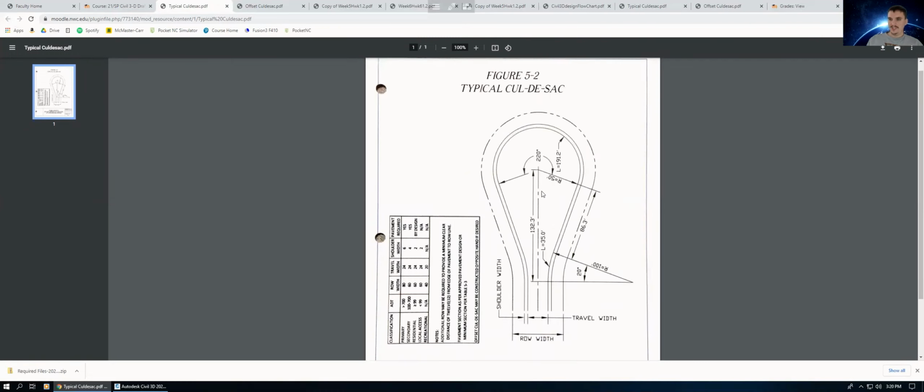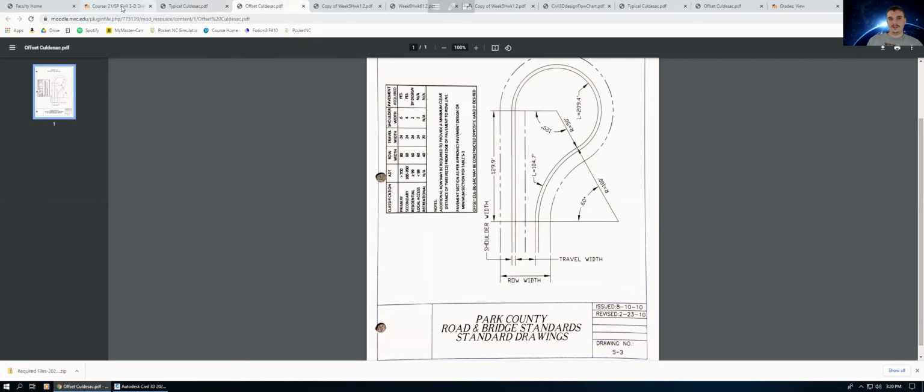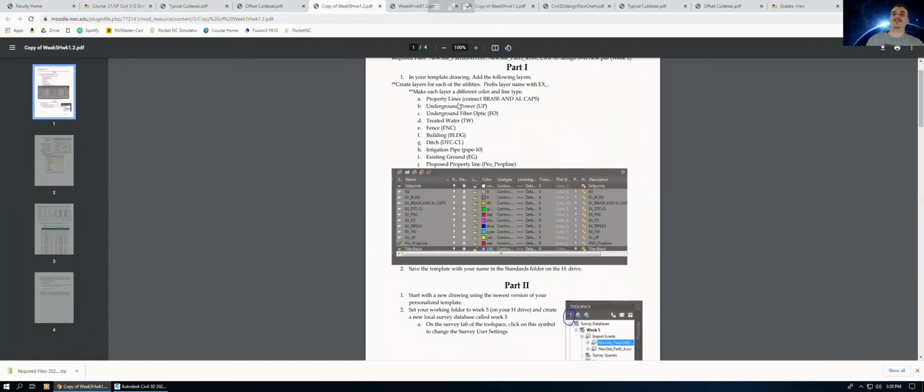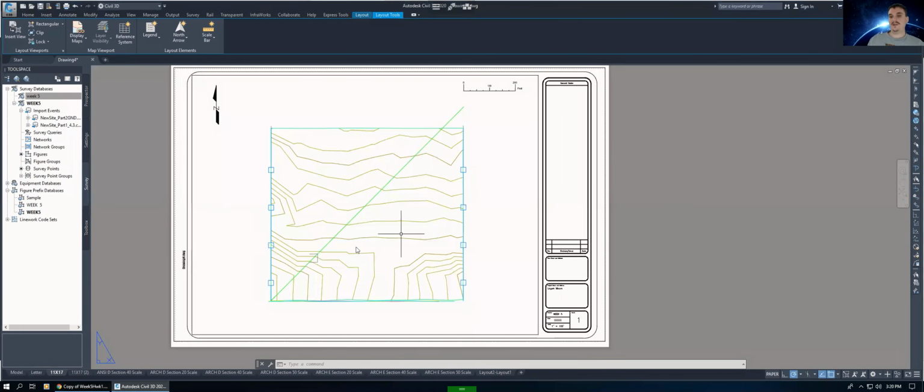So next week, we're going to actually draw this in CAD, but I want you to get a feel of how to look at a piece of paper and draw something to scale, or to look at something that's drawn to scale. A lot of the times I would work with engineers, and after I print something out, they would literally use their engineer scale with a pen and draw something, and then want me to measure that on paper and draw it in CAD, right? So when you print this guy off, I want you to grab your engineer scale, make sure you're on the 10 side so everything's golden.